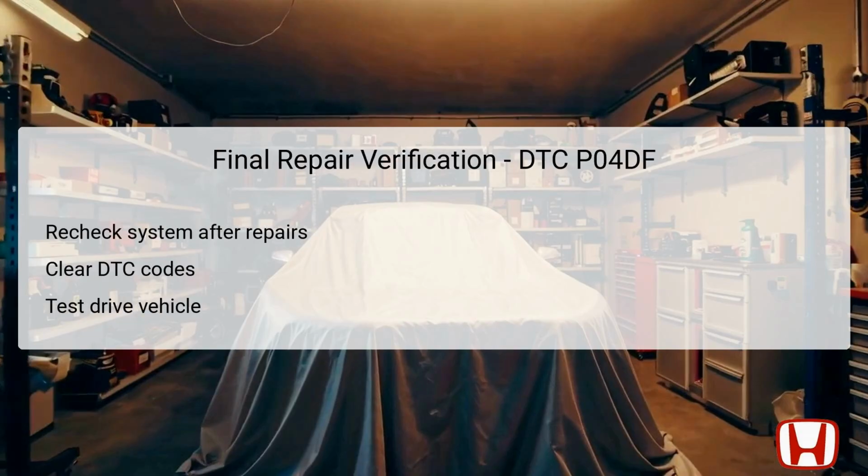Once repairs have been made to either the evap canister purge valve or vent shut valve, the final step is to verify that the repairs were successful. First, the system must be rechecked to ensure that all components are functioning normally and that there are no lingering issues. After completing the inspection, it's crucial to use the HDS to clear any DTC codes stored in the vehicle's memory. This action ensures that the system can refresh its state and accurately reflect the current operational condition.